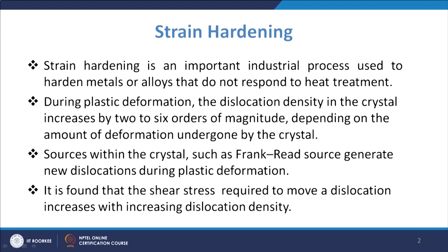When you do the plastic deformation, the dislocation density in the crystal will increase by 2 to 6 orders of magnitude, depending upon the amount of deformation undergone by the crystal. Since there is an increase in the dislocation density, that leads to an increase in the stress required for plastic deformation.